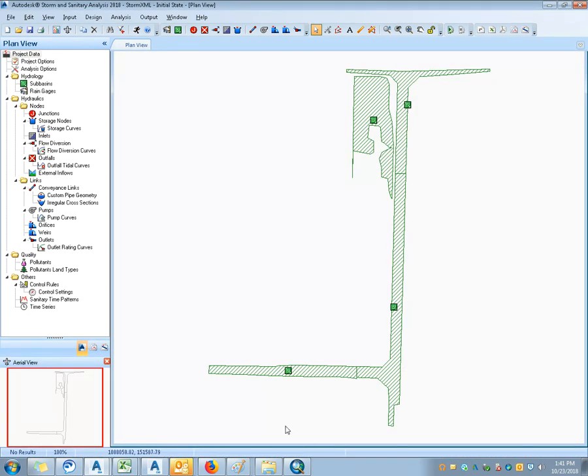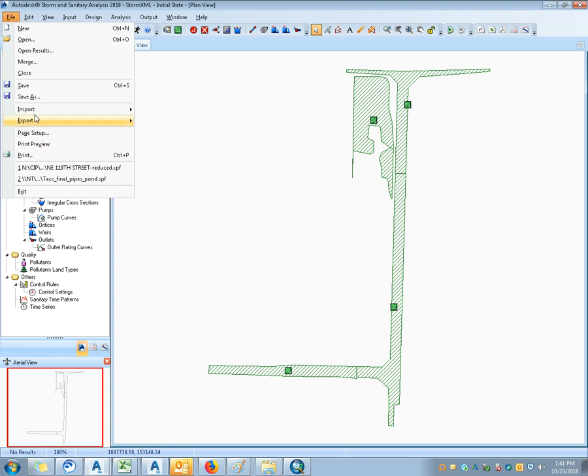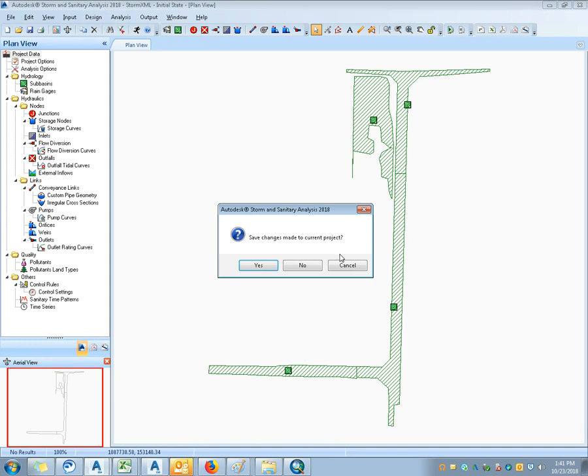So I drew it in, and this is data that I've drawn in from XML, from Civil 3D. So it's pretty cool. It pops right in. It draws the area, which I think is really valuable. The thing to know, though, is that once I've brought in an XML, I can't bring any other XML file on top of it. You can basically only bring in one LandXML for each drawing.